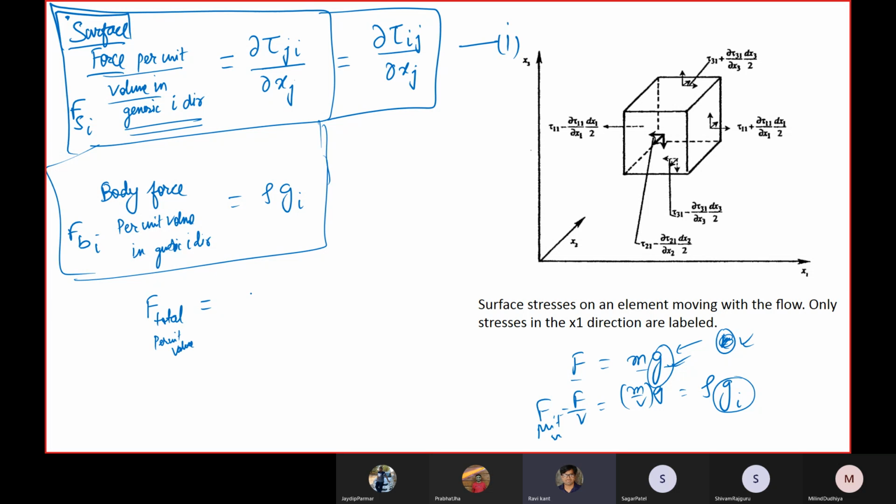In the Lagrangian description, we have written rho times capital D ui by dt, and this capital D was my total derivative. And this I can again write as rho dou ui by dou t plus rho, I will take ui common.